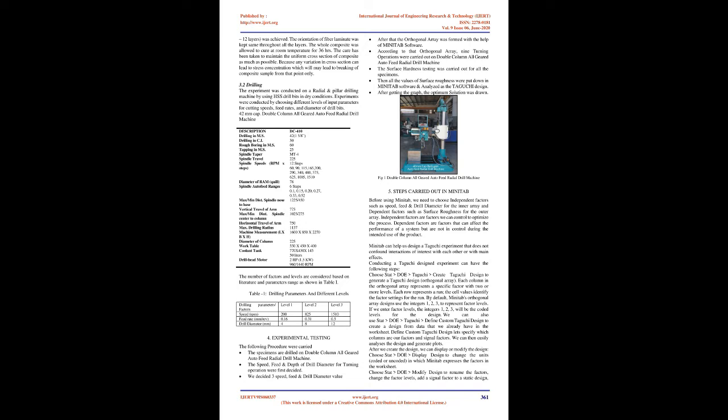E-glass bi-woven fibers were cut according to the size of the mold. The gel was sprayed inside the mold as a releasing agent. Alternate layers of epoxy resin with hardener and e-glass fiber laminate were placed until the desired thickness of 1 cm, 12 layers, was achieved. The orientation of the fiber laminate was kept the same throughout all the layers.